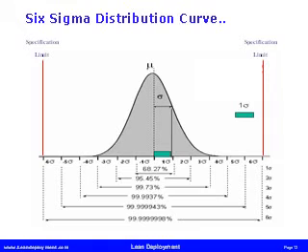When we talk about Six Sigma, what do we actually mean? Well, sigma is used to represent standard deviation, a measure of variation of a population. The term Six Sigma process comes from the notion that if one has 6 standard deviations between the mean, which is the centre of a process, and the nearest specification limit, there will be practically no items that fail to meet the specifications. This is the basis of the process capability study. The term Six Sigma has its roots in this tool.